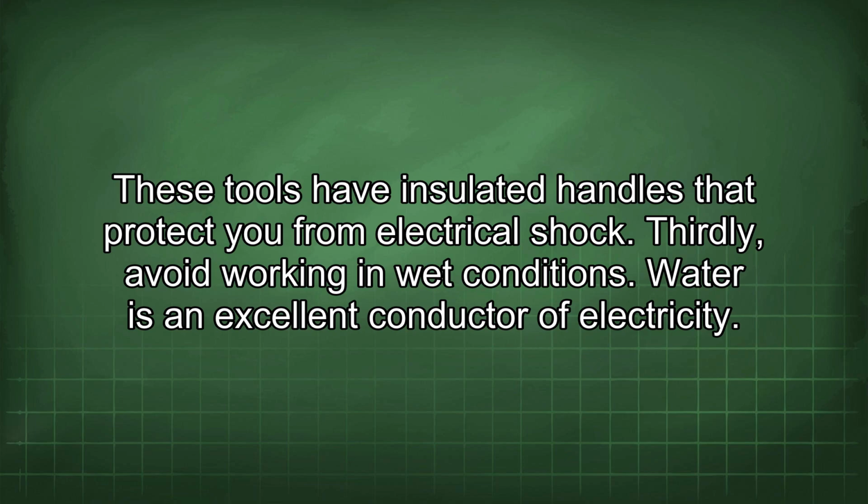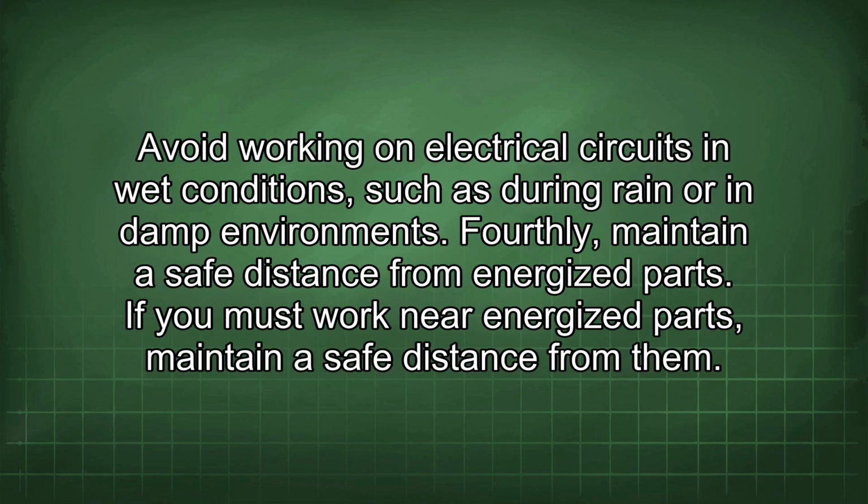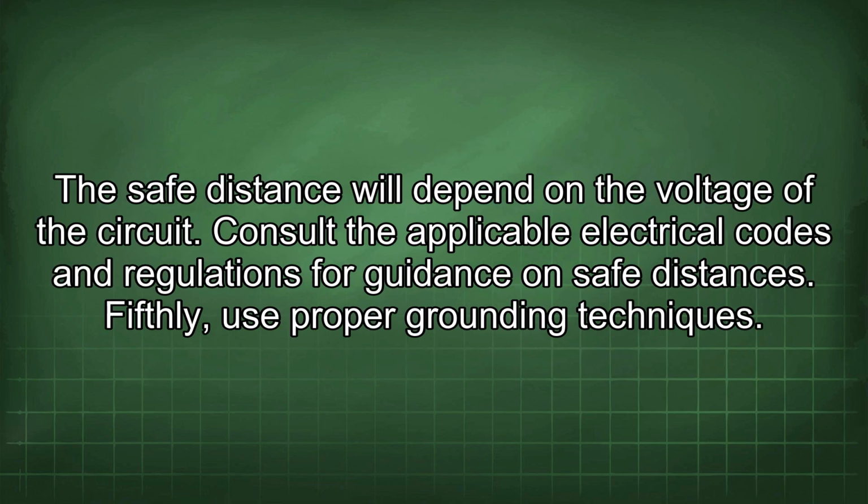Thirdly, avoid working in wet conditions. Water is an excellent conductor of electricity. Avoid working on electrical circuits in wet conditions, such as during rain or in damp environments. Fourthly, maintain a safe distance from energized parts. If you must work near energized parts, maintain a safe distance from them. The safe distance will depend on the voltage of the circuit. Consult the applicable electrical codes and regulations for guidance on safe distances.